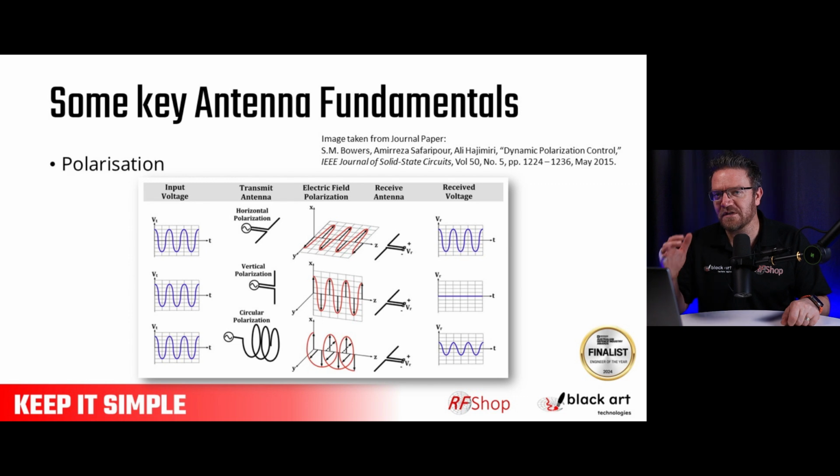The other one is polarization. So the focus that I have here is very much on outside the antenna. Now, of course, you set it up with the antenna, so the antenna needs to launch into a certain polarization. We are used to, if you look at TV antennas, again, going back to consumer experiences, there's vertical, there's horizontal, different areas in Australia, in the world where you go, you would see antennas standing differently. That's the polarization. Circular polarization is a little surprise factor that gets used more in the mining and in the tunneling industry, underground industry. Let me show you why.